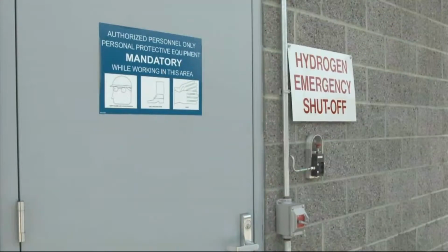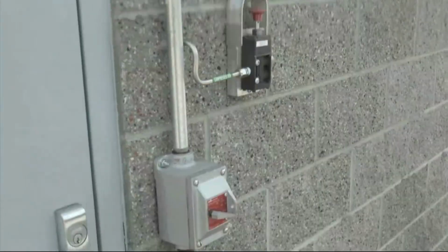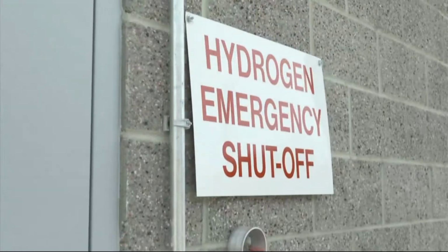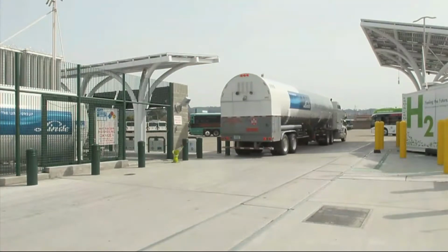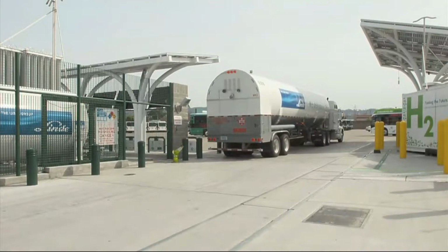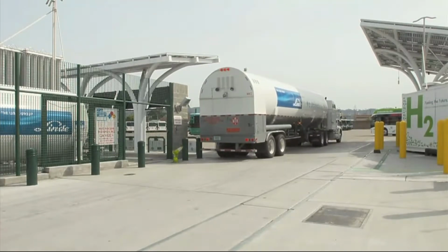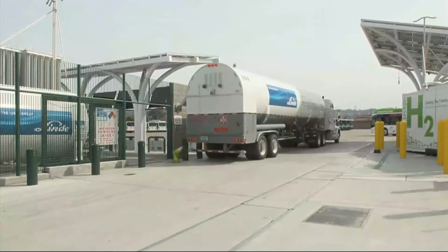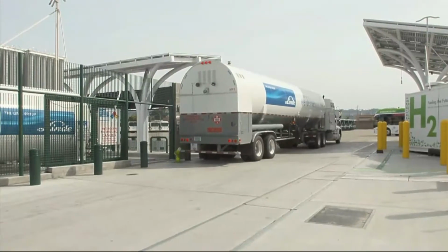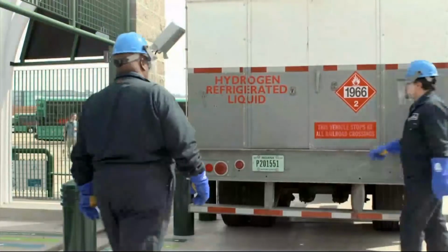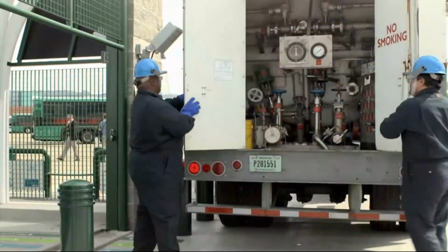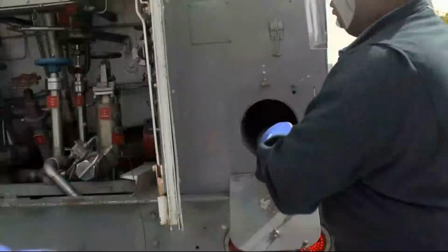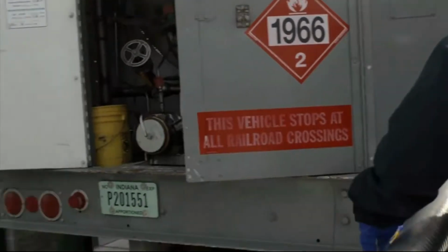In the event of a leak or other emergency, an emergency stop button is available that will shut off the supply of hydrogen from the tank. The area around the storage tank should be kept clear of material, cars, and other vehicles. Backing in a gas delivery truck takes a lot of room, so be sure to maintain a wide, clear path from the road to the storage tank. The tank on a gas delivery truck is basically the same as a stationary tank, double-jacketed, holding liquefied hydrogen under low pressure. Only trained industrial gases delivery persons certified in hydrogen handling systems should handle unloading.